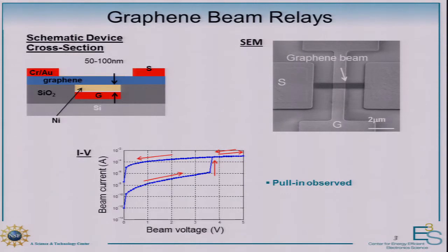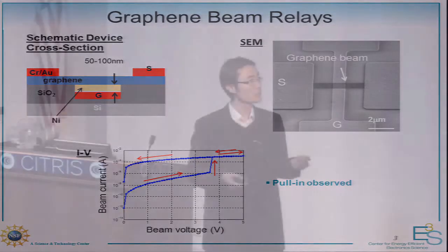I saw Dr. Feng; he actually had a graphene beam relay which was released. But for us, it was not so easy to see the release of these graphene beam relays. We think this is mainly because of these atomically thin structures. There's really limited restoring force after contact. Although if you design in a certain dimension, we may be able to see a release of the structure.